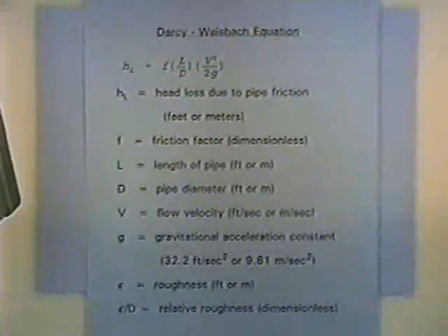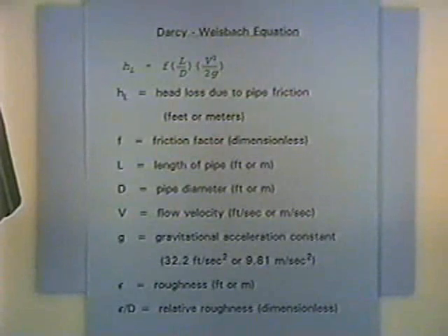Using that software as an example, but other software as well, they'll have options to use either Darcy-Weisbach or Hazen-Williams. All the textbooks will show both methods, and we'll talk about both methods as well. So two approaches to doing the same thing, estimating head losses. Both are empirical equations. Darcy-Weisbach is more theoretically correct, and we'll point out the reason for that. So we'll present it first.